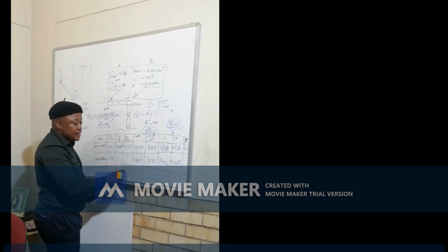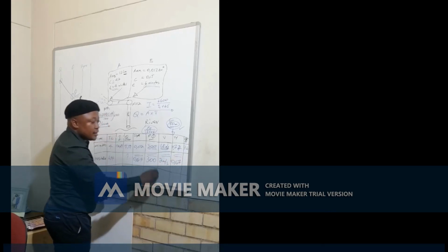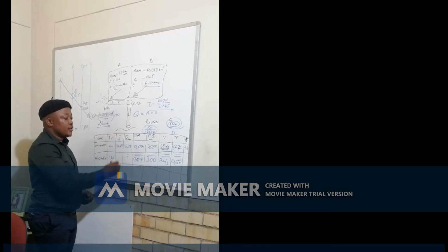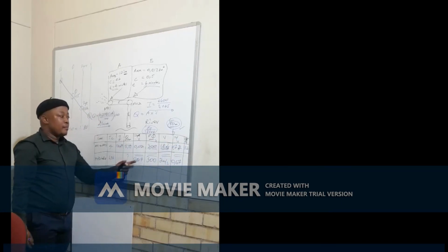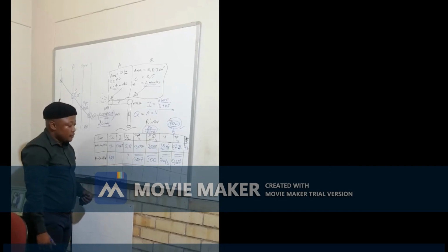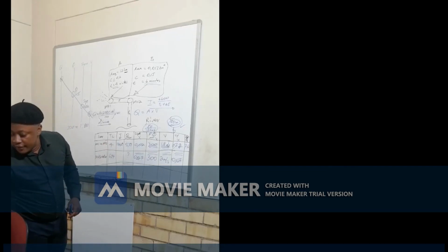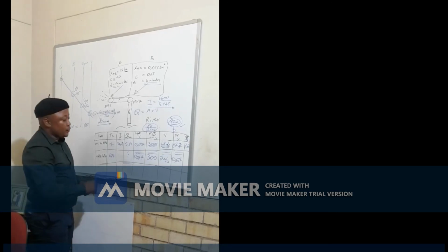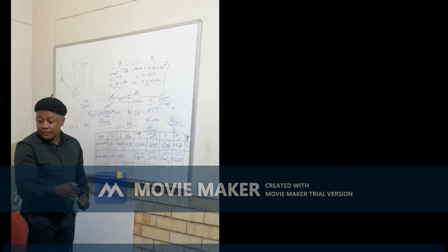Now, for you guys who are watching this video, you can go ahead and practice the same calculation and try to discover whether you also get similar variables, and make sure that you understand how to solve that part of the equation, because that is where you'll probably have to make use of the nomogram that has been shared again with you on Blackboard. Now again, after substituting, we did get the variable for the intensity, and the intensity was sitting at 127.56, and then the flow that we designed for was 5.88.